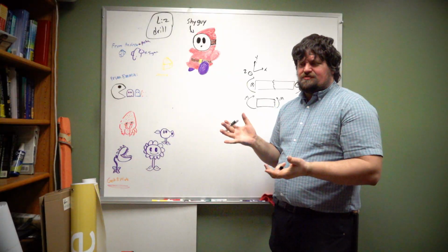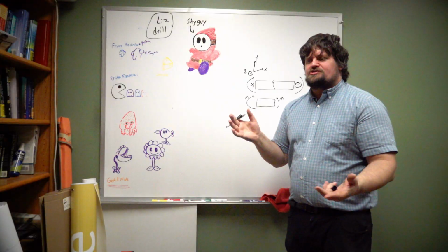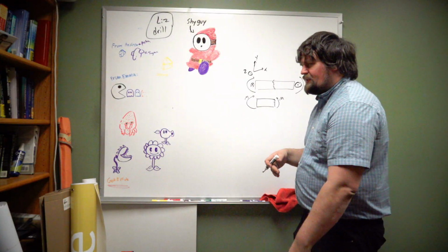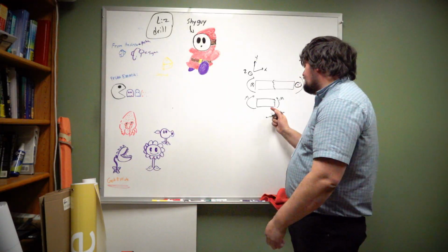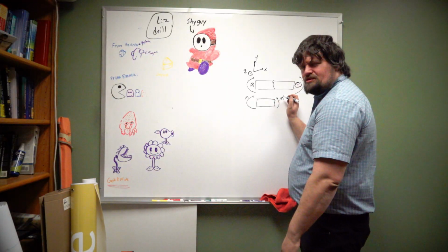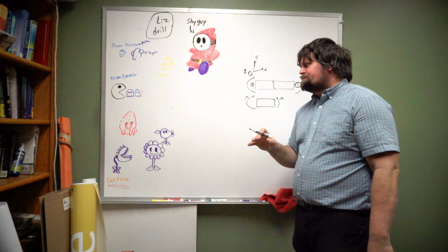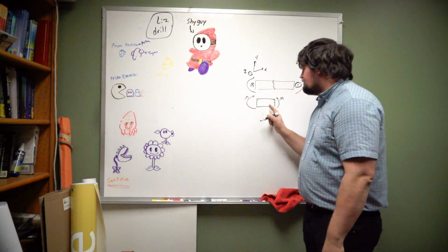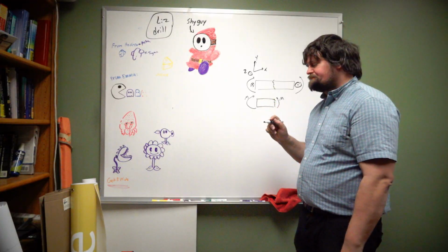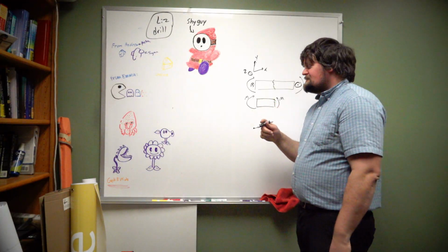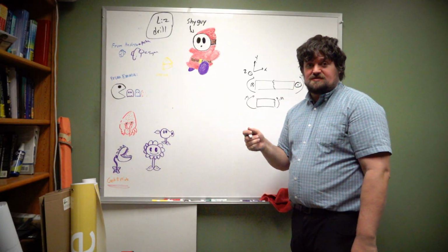intermolecular forces. Intermolecular forces don't actually have the ability to impart a moment on each other when they're just touching each other. There are ways of doing that, specifically magnetic or electrical ways, but quite frankly, we can't just exert a moment. Whereas what we saw in the axial load and the shear load, where it was just a summation of all of the intermolecular forces across here, we aren't adding a sum of moments. So what we see instead is that there has to be some kind of net moment, and that net moment has to be in the Z direction.